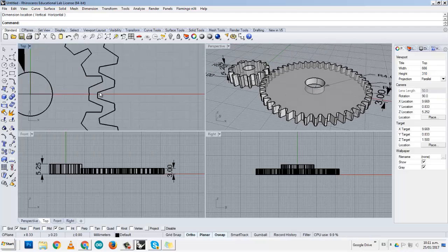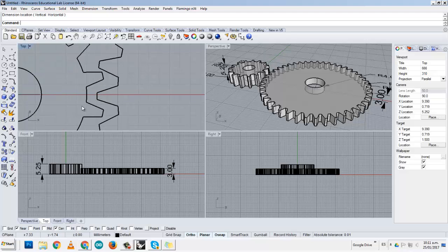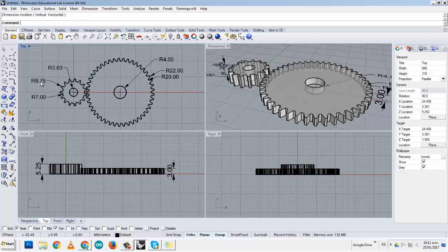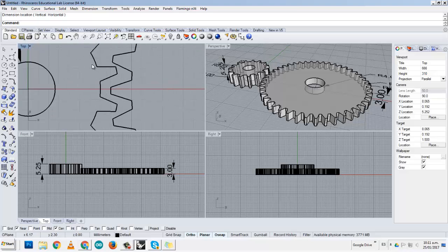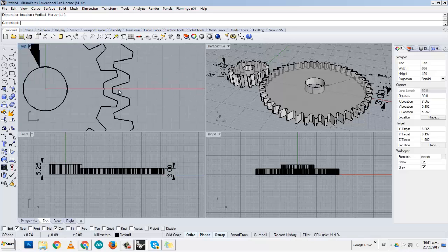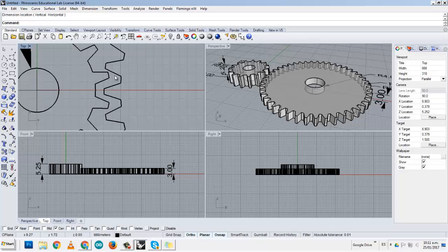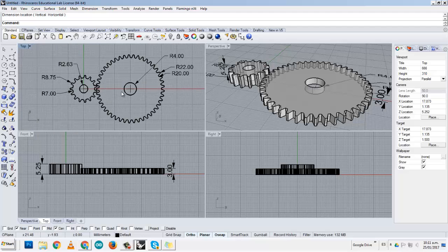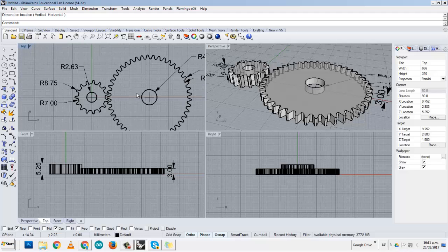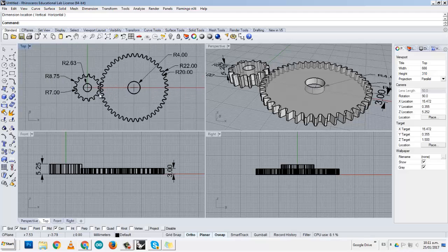As you can see here, this is not an accurate configuration for a gear, although this is the way that you can actually design gears on Rhinoceros. When the 2 gears meet, you should make sure that the addendum line goes over here and is tangent to the other one. So right now these 2 gears wouldn't be accurate for building, but we can actually make them in 3D.